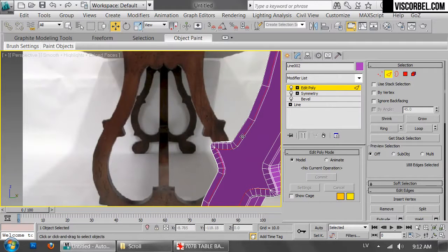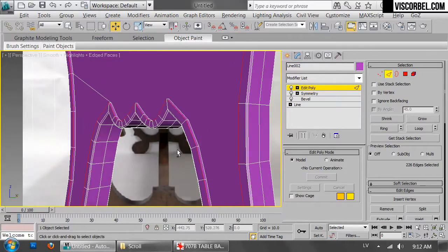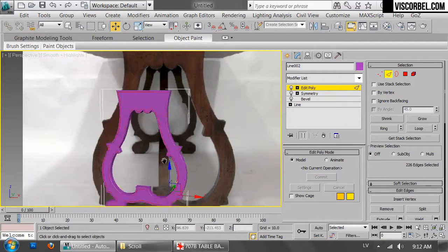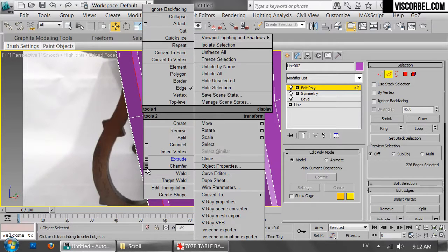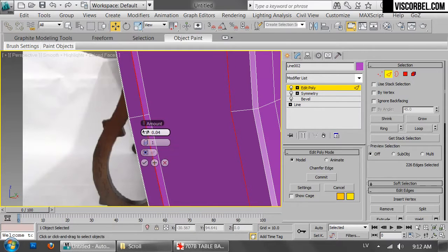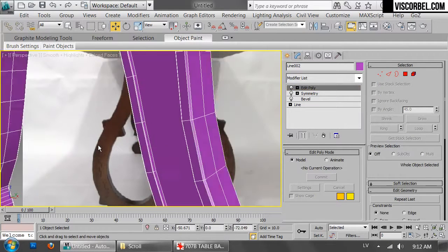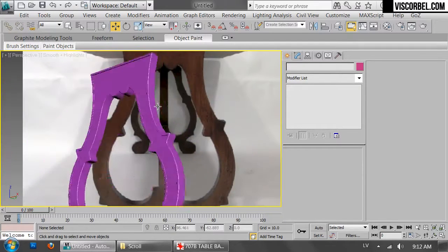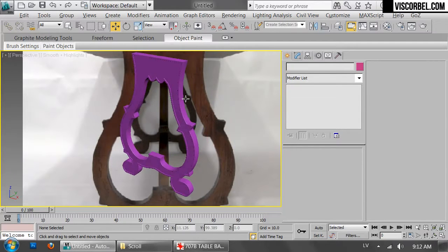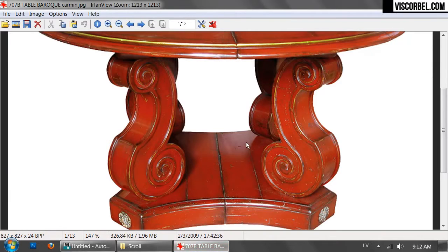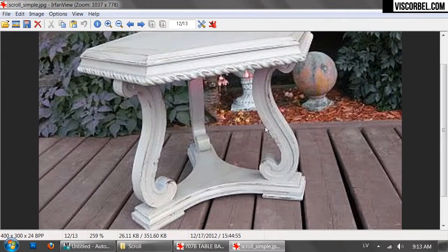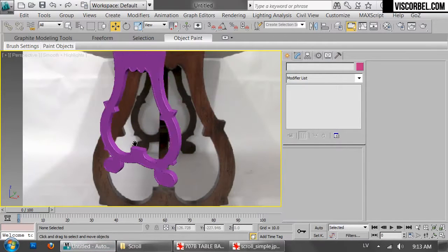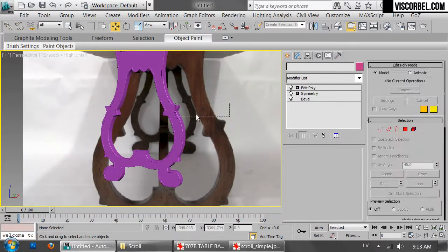All that's left is chamfering the edges. I should probably have increased the interpolation steps for the original line, since it's a bit faceted over here, but I just want to demonstrate the principles of how to create something like this. Okay, so you have this decorative border here, and it works fine if it doesn't have these scrolls that go inside the shape, and if you only have a border, like for example in this photo, you only have border, no details inside. So that's something like this.